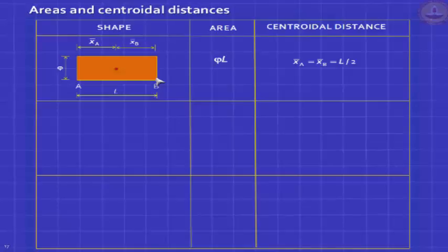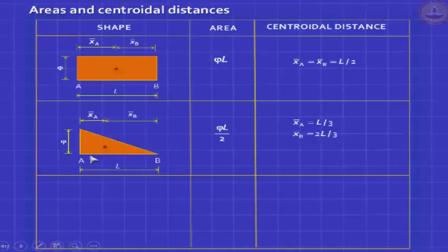Bending moment diagram can have any funny shape. So you should quickly be able to find the total area and the centroid. For a rectangle, very clear, if the height is phi, it's constant, then the area is phi into L and the centroid is bang in the middle. If it's triangular, area is simple, it's half that of an equivalent rectangle and the centroid is located at a distance 1/3 to 2/3. This is all common sense, we know that.